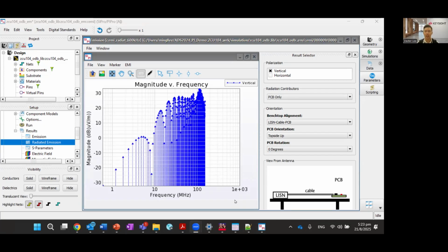In summary, I've gone through some of the tips and tricks to resolve SI analysis, looking at the eye diagram, how to identify whether there's crosstalk or a serious frequency-dependent loss issue, and how to work with equalizers. And then, of course, we've gone through a few labs on ADS, looking at the very basics of how to run channel simulation and look at the eye diagram.